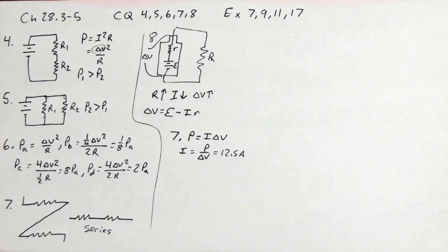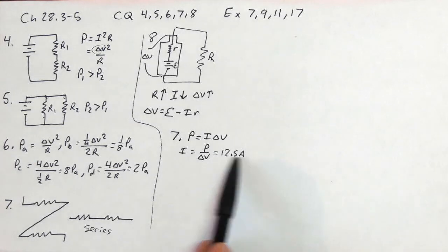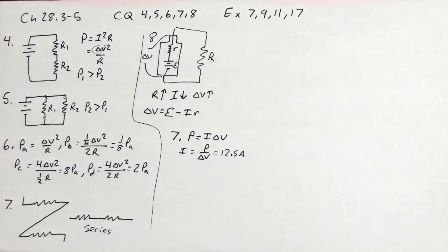Basically, it detects how much current's flowing in and how much is flowing back out. Because remember, this is a circuit, so current flows from your power source in your house, from the power panel, and it's got to flow back to the power panel. It has a little detection that says if some is flowing elsewhere, meaning through your body, then it shuts off, at a very small amount, extremely small, smaller than what would kill you. So it's a protection, very necessary for things like hair dryers and toasters, things that would be around a water source, where water can be a good conductor with the minerals that are in it, usually in a household supply.